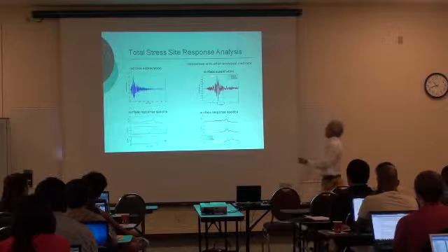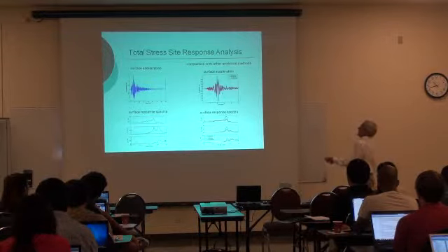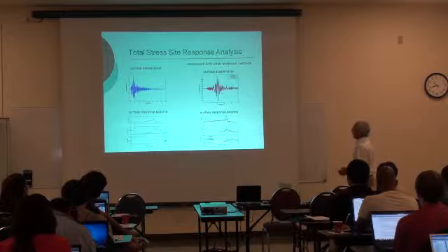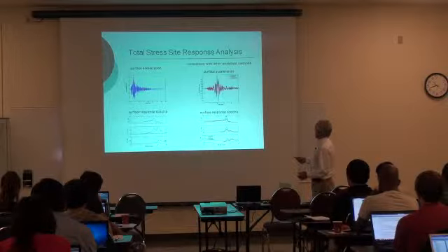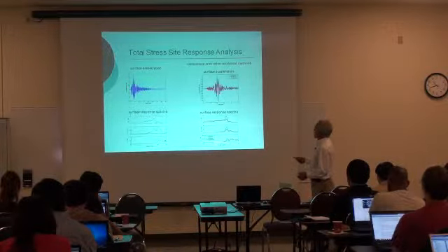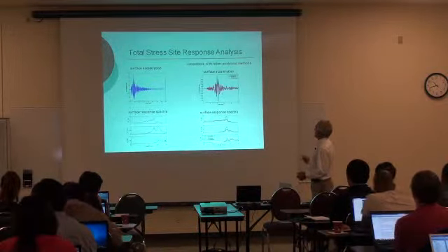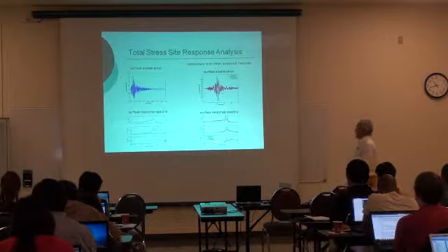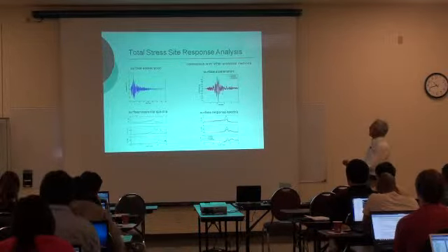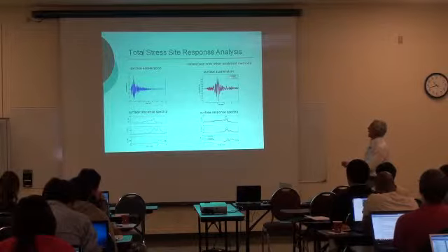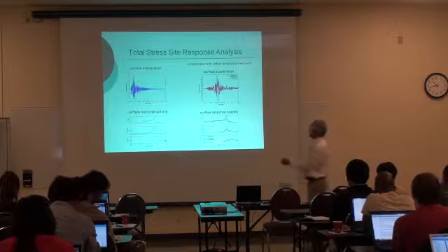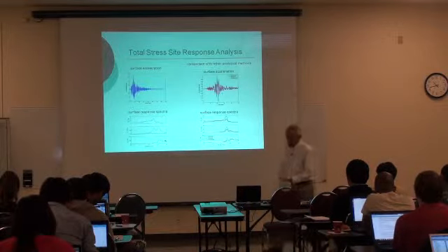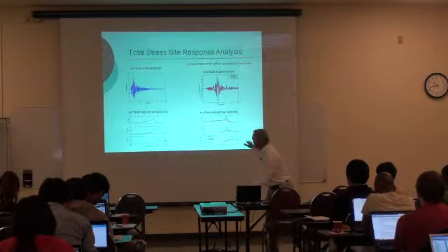Again, we compared with Shake. Shake is the typical thing that is used. This is the acceleration time history, and then this is the surface acceleration that you have in the model, and we compare OpenSees with ProShake and some other tools, both in terms of the time history and also the response spectra, to see if we were getting close or not close.